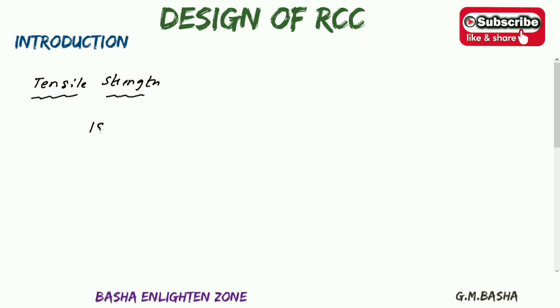So, according to our Indian standard IS 456:2000, the tensile strength of concrete can be calculated from the compressive strength using the relation fcr equal to 0.7 square root of fck Newton per mm square. So all these relations you will get in the code book also. So you please remember, what is the relation for the tensile strength? That one will be fcr equal to 0.7 square root of fck Newton per mm square.